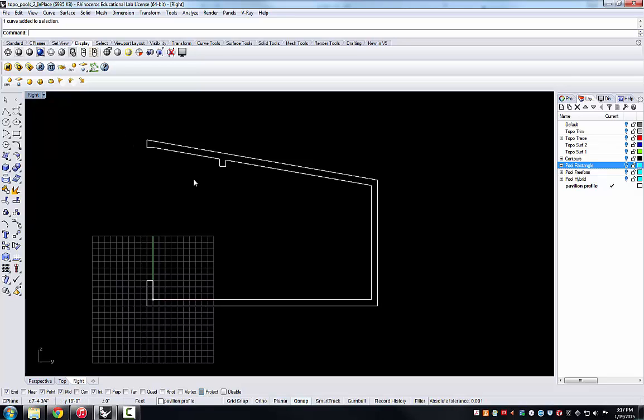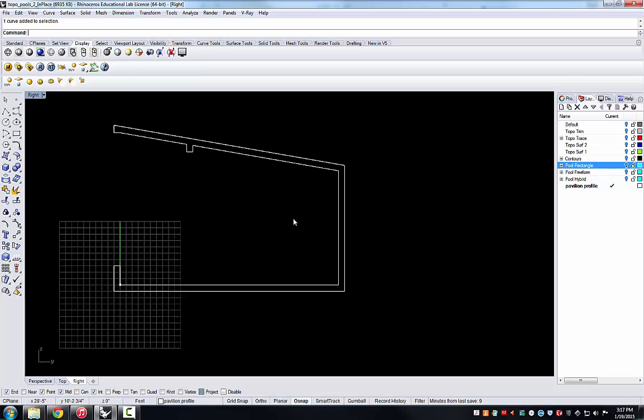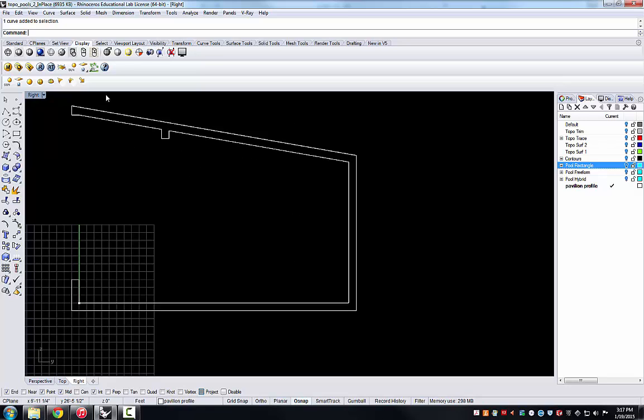of the pavilion. As I said, we're going to next draw another polyline. In this case, we'll start from the midpoint in height of the lower wall. We will come to the left a total of 12 feet, holding shift so that that's perfectly horizontal. And then we'll come down to the floor. The reason that I'm able to do this by selecting the midpoint immediately or the intersection is because my object snaps are on for midpoint and intersection.